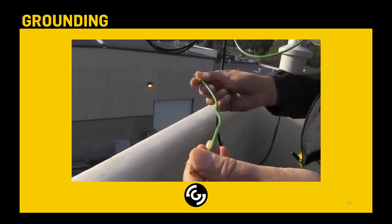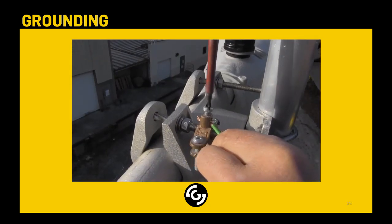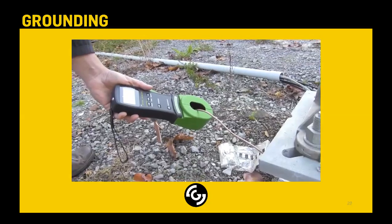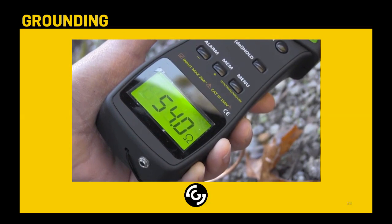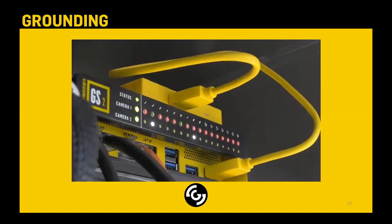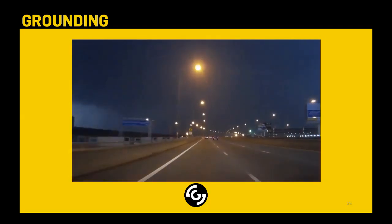To start, connect a 3 to 4 inch long piece of fine strand 10 AWG wire from the mounting pole to the mounting arm. Secure the ground wire using a self-tapping screw or a cold water ground clamp. Once installed, test the ground wire at the mounting arm with an ohm meter to ensure continuity. Then check the ground resistance at the base of the mast luminaire pole. Resistance to the ground should be less than 25 ohms. Also, if your mast arm is painted, a separate 10 AWG ground wire should be attached from the mounting bracket to the mounting structure. Again, your GRIDSMART system leads the industry in onboard surge protection, but if storms are a problem in your area, installing the extra surge protection is worth the effort and enhanced protection the next time Mother Nature decides to strike.